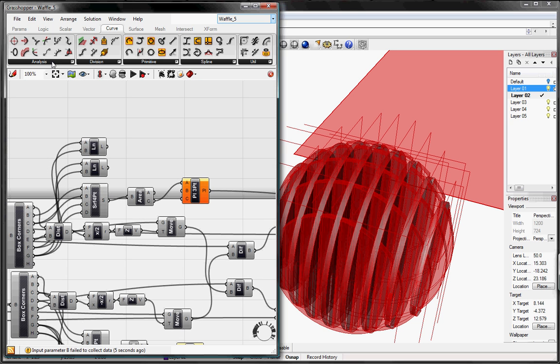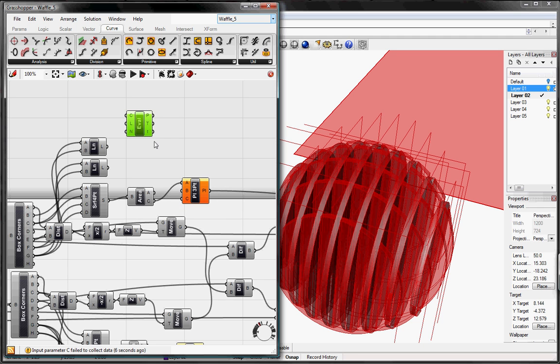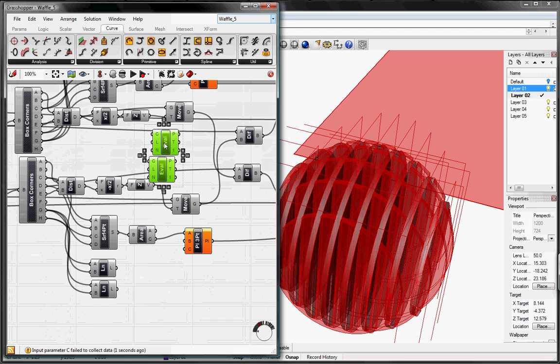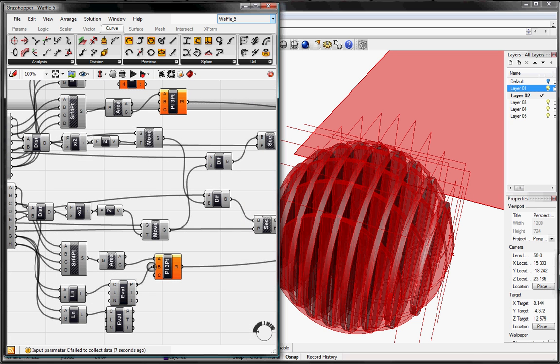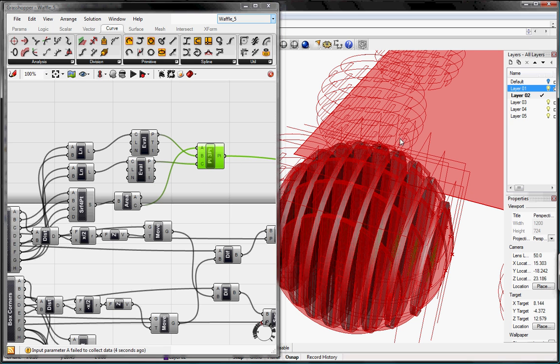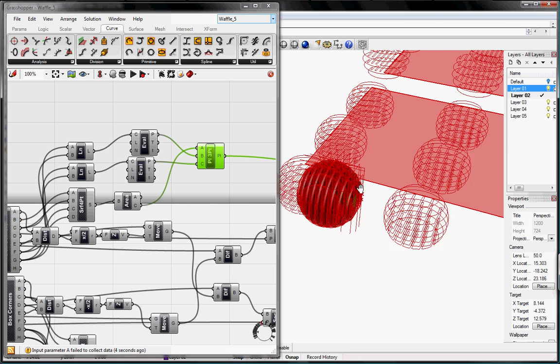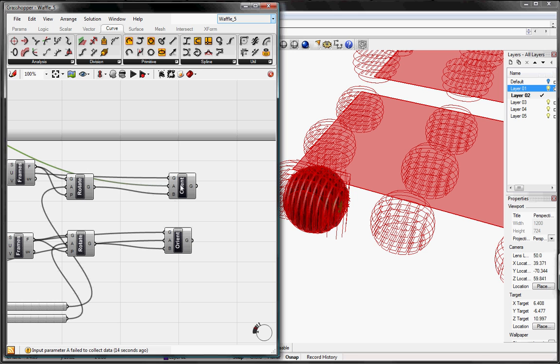And then we need to go to Curve, Analysis, and then Evaluate Length. We know that we want the midpoint, so instead of 0.00, we're going to say 0.5. I'm going to copy and paste this. I'm going to need 4, one for each of my lines. Connect the curves: P will go into B, P will go into C. So there you can see that our sections are now laid out onto our surface, except they're taking all our curves into all our frames.